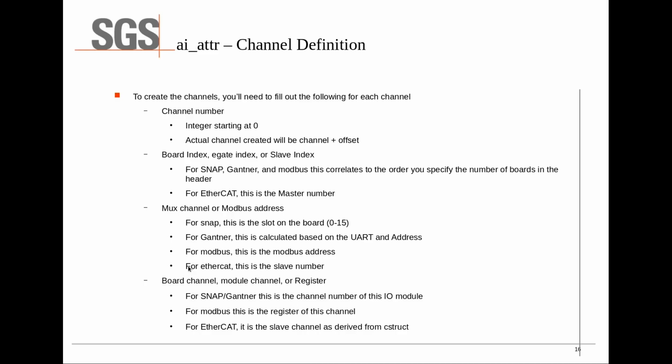We already talked about Modbus. For EtherCAT, this is the slave number. You'll run the EtherCAT slaves command. It'll show you all your slave devices, and then that's the number you're going to put in there.